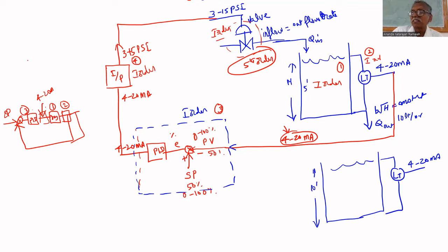Bike, let us assume that it is first order, maybe higher order. You are looking at the speedometer, which is connected in series with that. That is another first order. So minimum second order. You are looking at the speedometer through your eyes, third order. The output of the eyes is given to the brain, fourth order. The output of the brain is given to your hand, fifth order. That's why if you increase gain beyond a certain value, it may become unstable.